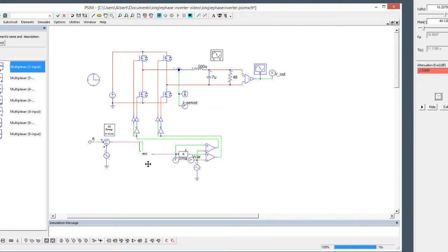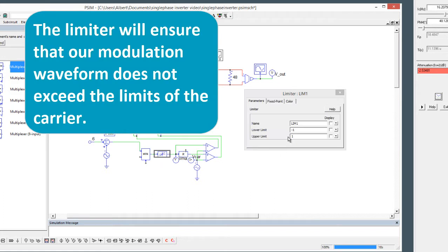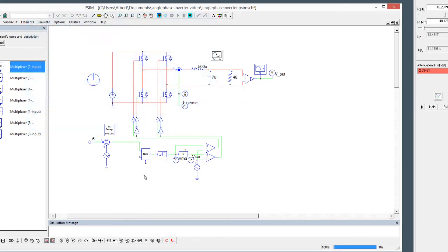Well, actually, what I'm going to put in to begin with is a limiter. So in the end, all we care about is -1 to 1, but maybe we'll reduce the maximum and minimum duty cycles to 98%. And let's now put in a PI block, and we'll move this again sort of out of the way a little bit more. Give me lots of room to work.